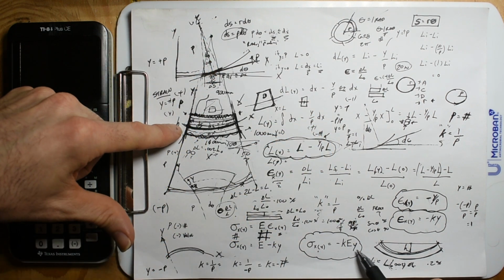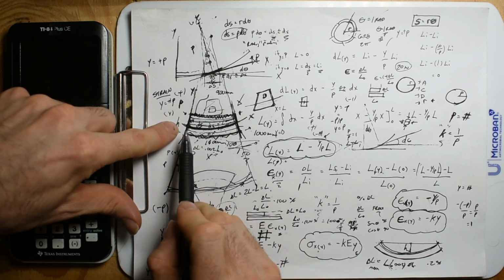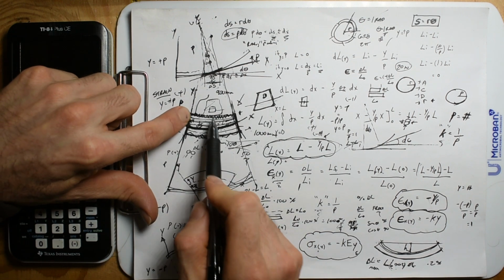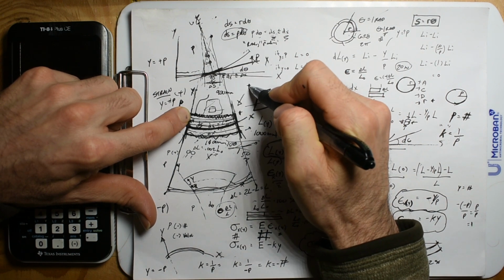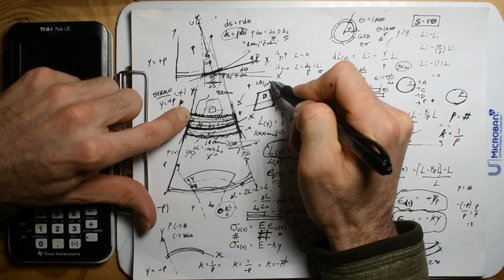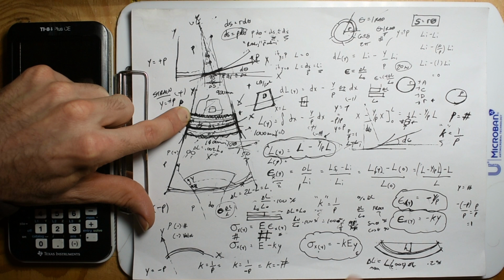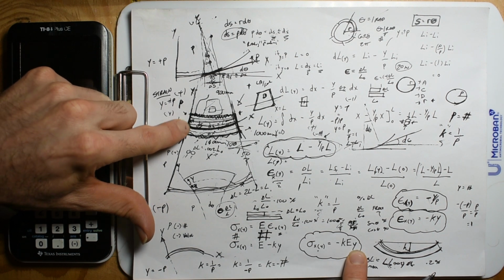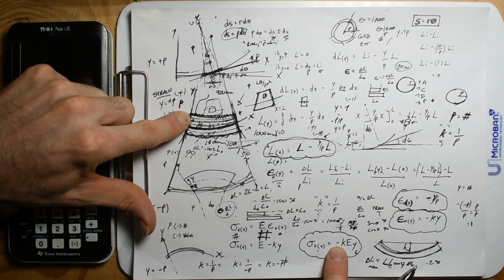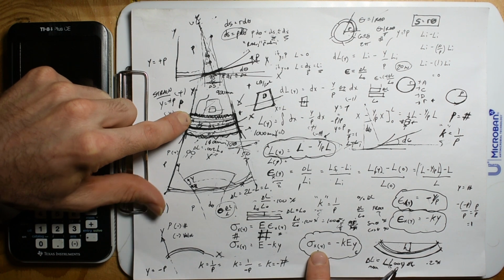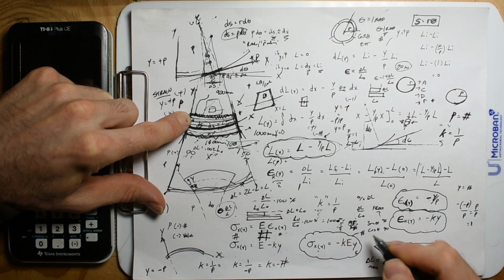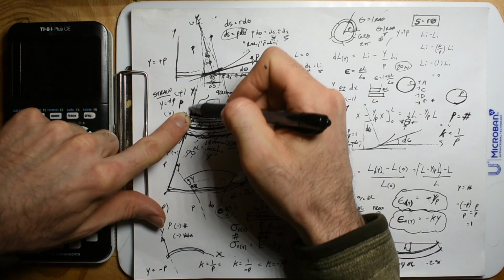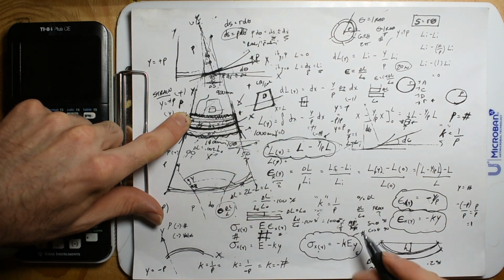And it's based on this Y. So if I throw in a positive value of Y, the pressure in compression should always be negative pounds per square inch. I should have a negative PSI. So that's what we have: a positive Y value, and this negative makes a negative PSI. This is a constant, just a number. Our K, given this, had positive curvature, so K is positive.